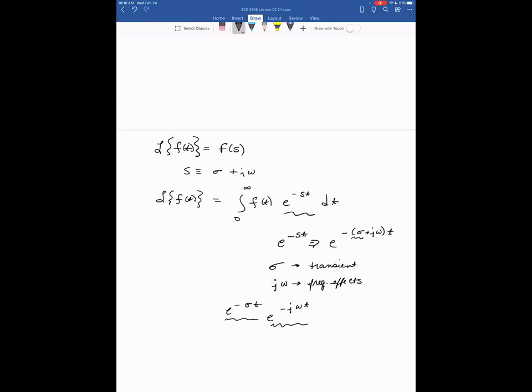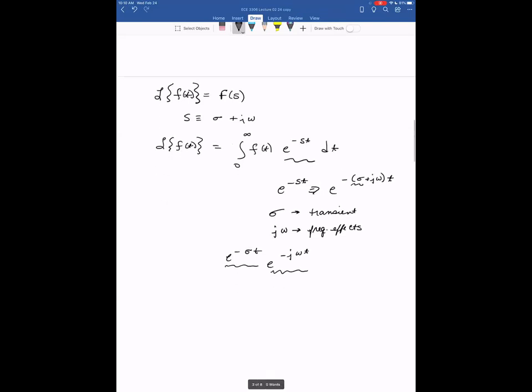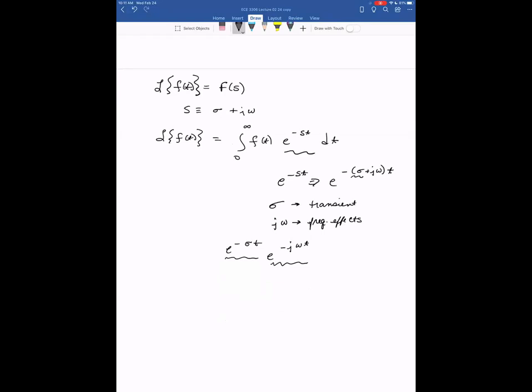It also encompasses ways to take into account initial conditions, which are important in transient circuits. If we have things like charged capacitors that we're switching over to inductors or switching over to an RL load, then it enables us to do that and to take into account those initial conditions. What it does not do is it does not allow us to model for anything less than t equals 0. So you've always got a system that is being switched on at 0. It can model transients for t greater than 0, but it cannot model transients for t less than 0, because